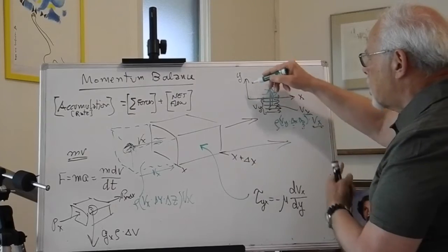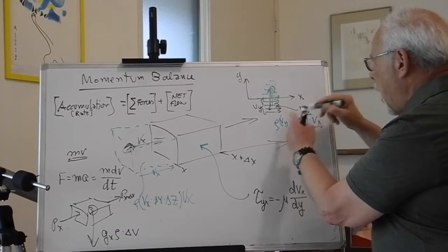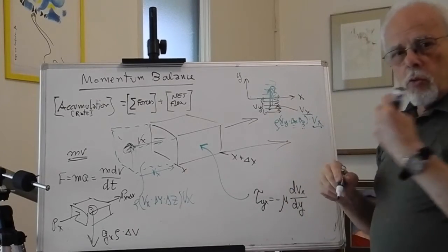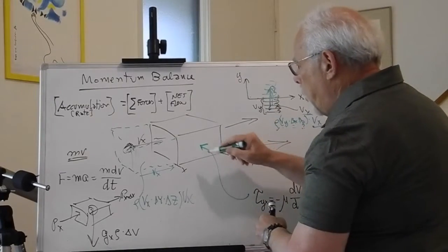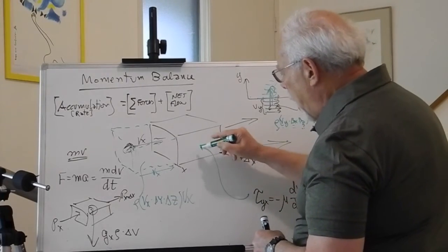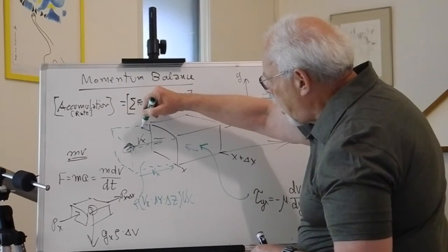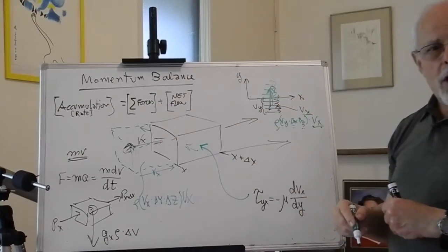So that is the rate in which momentum enters through a cross axis. The Vx momentum enters through the y-axis. Same expression through the z. And again, what enters through the y direction then has to be subtracted by what goes out from the opposite face.